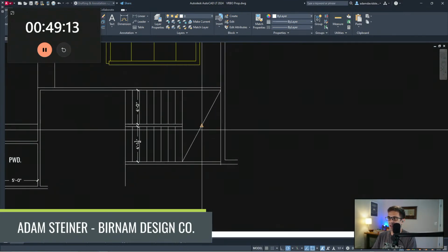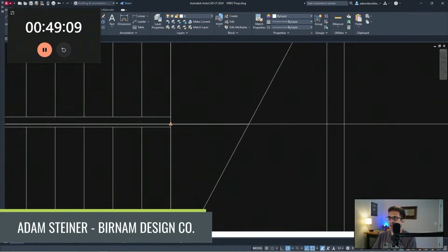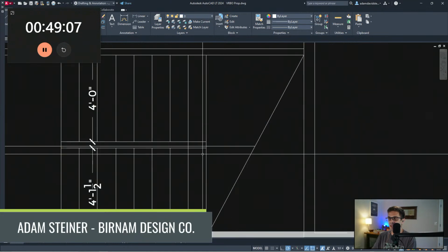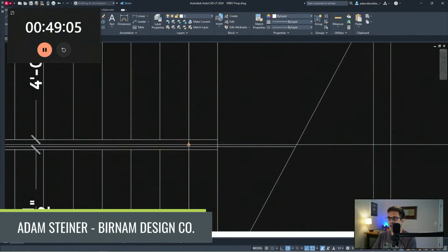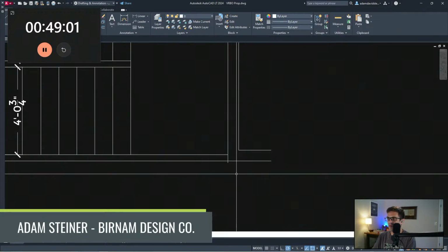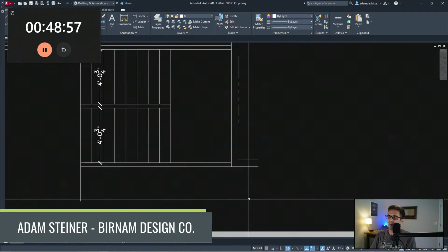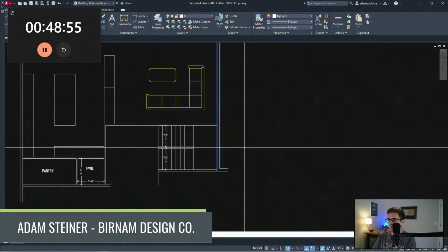Usually gets to a little less waste, but doesn't work out 100% of the time, and that's okay. But you really want to end on even inch increments where you can. At least the concrete companies I've worked with don't have 1-inch forms. They have to custom make them. It just gets annoying. So the forms usually go down to every 2-inch.